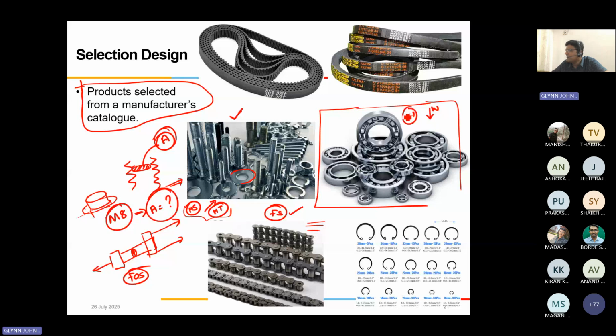What is the RPM, right? What is the expected life, right? How many million revolutions, right? So how many years? Every 5 years you want to replace your bearing, or you want to replace your bearing every 10 years, 15 years. So based on that, you choose the life of the bearing, and put together, you will get the probability of survival, right? So now how long do you want this bearing to last under the given load? So you will, based on the probability that you want.